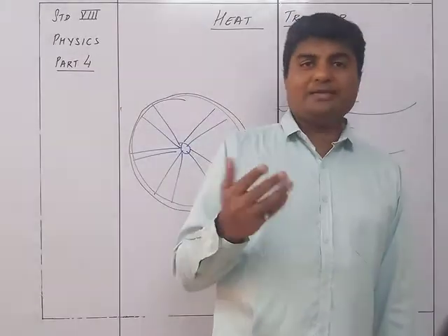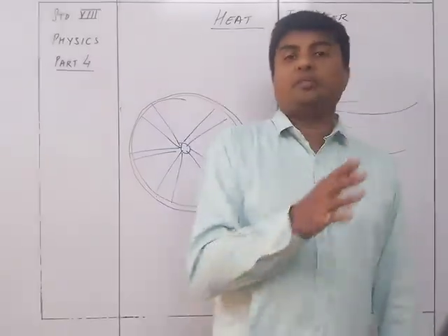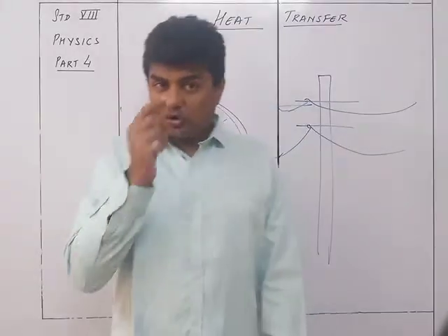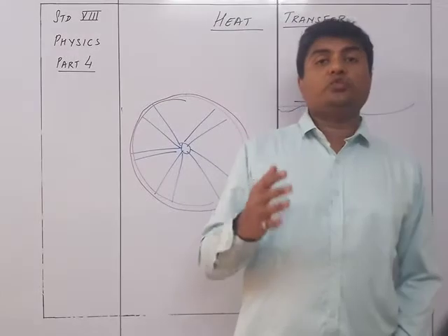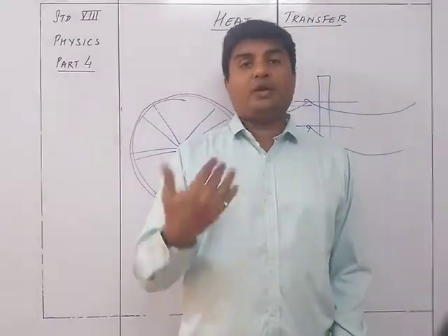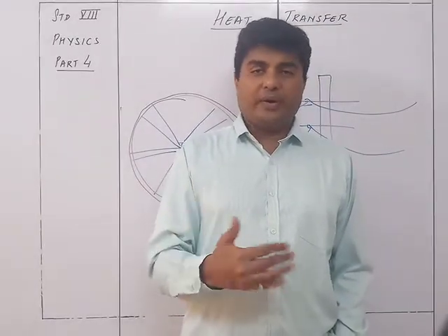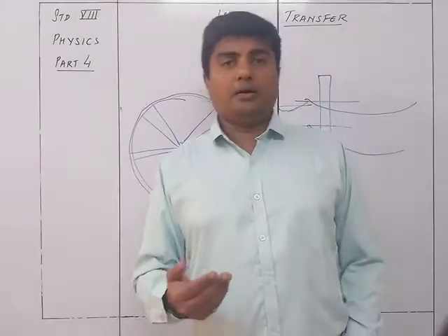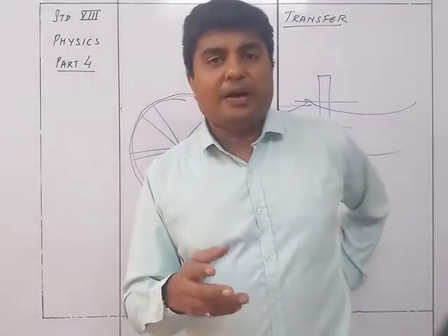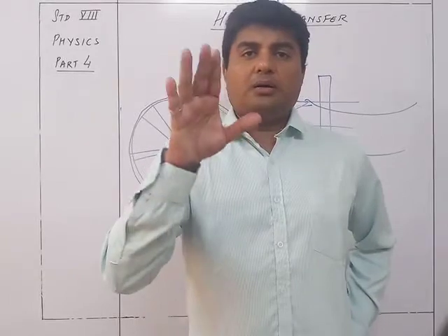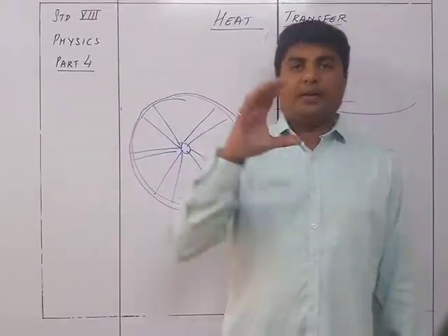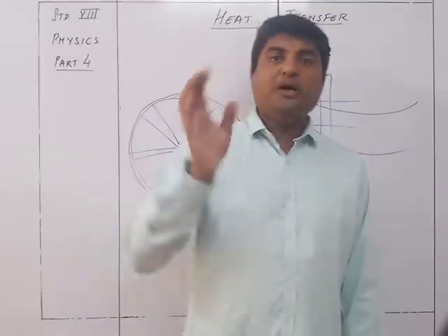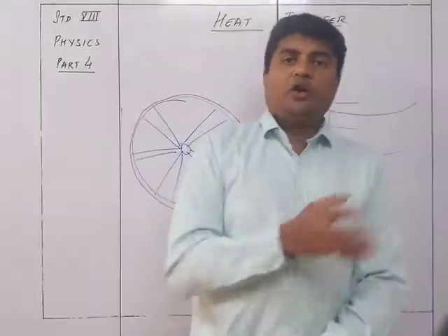In olden days, the clock did function because of the movement of the pendulum. If the pendulum is made of a material that would expand and contract due to heat, due to summer and winter, it matters, because the time period is dependent on the pendulum's size. If the size is smaller, it will be faster. If it is longer, it will be slower.